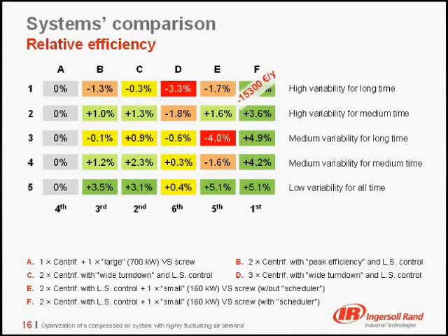System C, yes, it has just a bit higher operating cost versus system A. But for just 1,500 euro savings per year, for the reasons explained before, it means spare parts availability, backup compressor and so on, I personally would rather prefer to have two identical machines in my plant instead of two different machines.